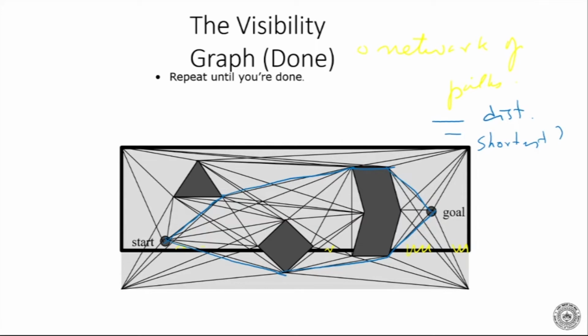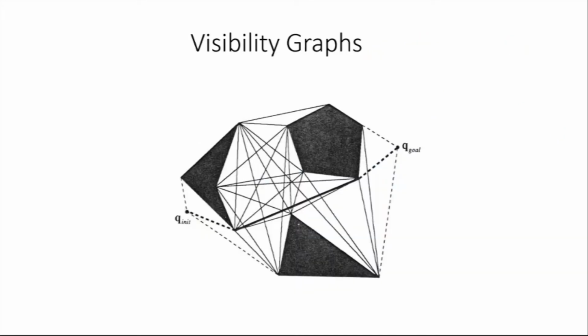So this is basically called the visibility graph method, where we have drawn the visibility graph simply by connecting all the vertices by straight lines. It's like you go and stand on a vertex, and whichever other vertex is visible to you, just connect it with a straight line. Now this is a visibility graph where we have drawn the complete graph.